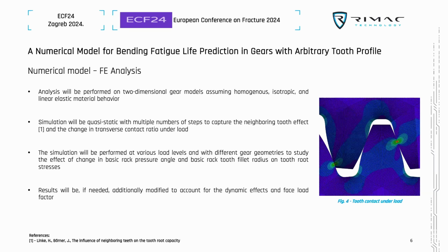Also, the results can additionally be modified to account for the dynamic effects or the face load factor. Face load factor being the unequal distribution of load along the length of the gear tooth, which cannot be taken into account using a 2D simulation, of course.